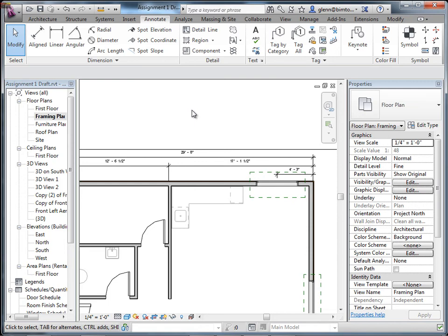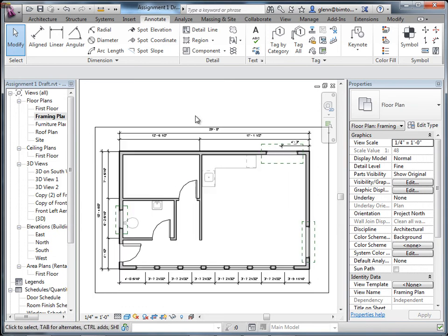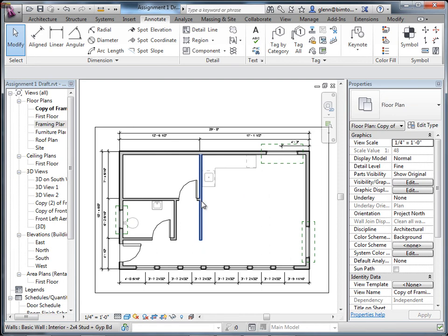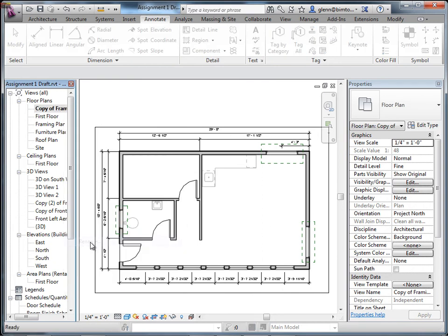Okay, so I got a nice dimension drawing here. That's looking pretty good. The nice thing is now, if I have a nice dimension drawing here, if I want to go through and create another view, for example, I'm going to duplicate this view, and I'll choose Duplicate with Detailing. Okay. I now have one. The dimensions got copied over to it. So you can sort of decide. What I'll often do is actually dimension and kind of use that one as the basis for doing a lot of copying from here on out. Let me call this the floor plan.